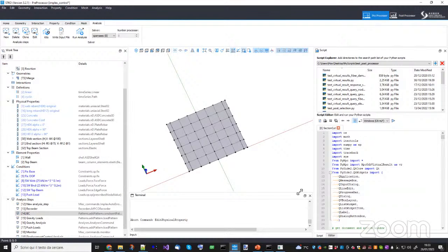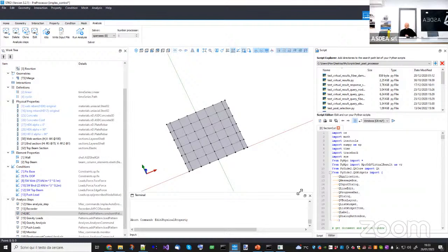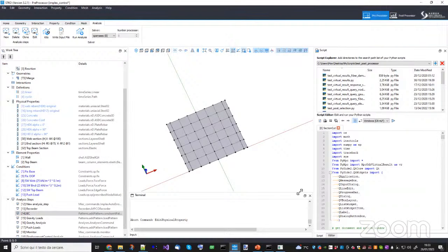I don't have questions, just comments. A good idea could be also to test that model with materials with low modulus of elasticity, like adobe, earthen materials. When we are talking about 200 megapascals, we found, for example, in Concrete Damage Plasticity in Abaqus, that we had some problems. So it could be good also to test this model with low elasticity modulus materials. And again, congratulations and thank you very much.